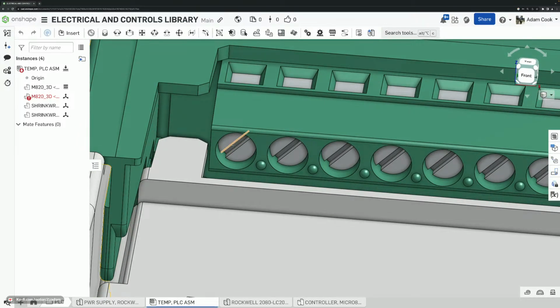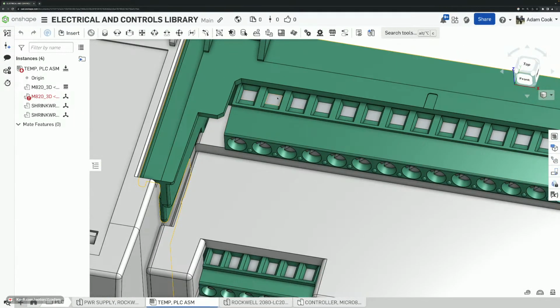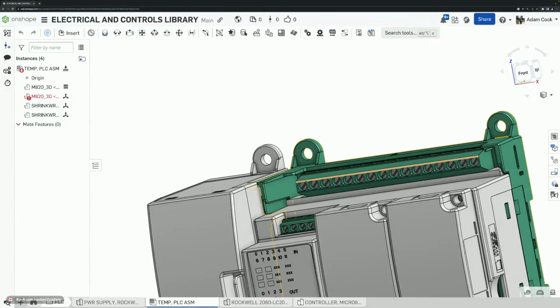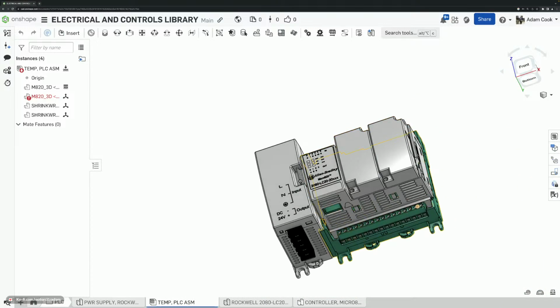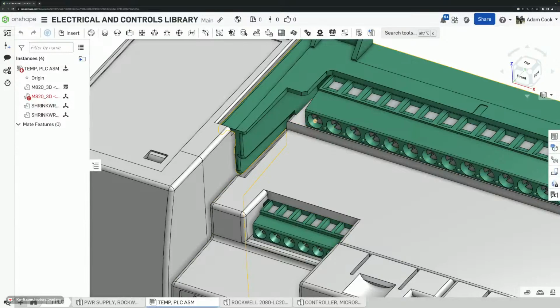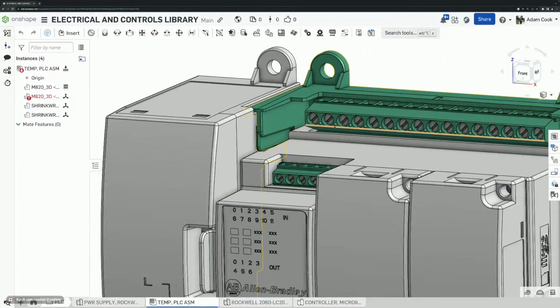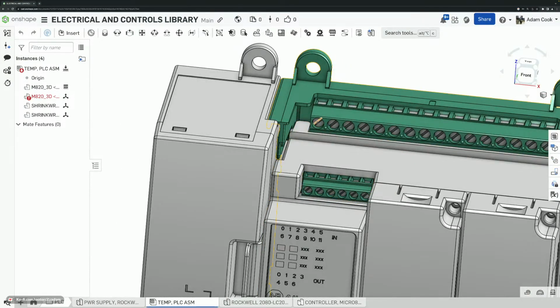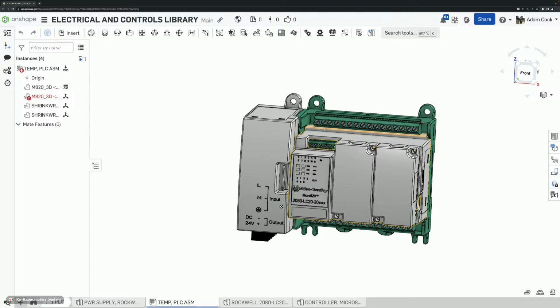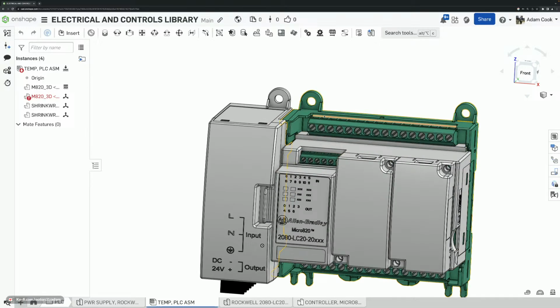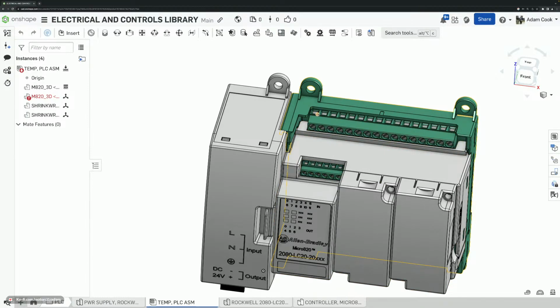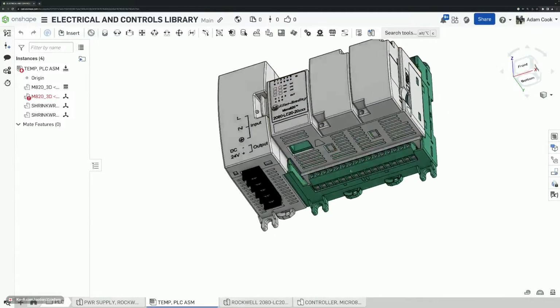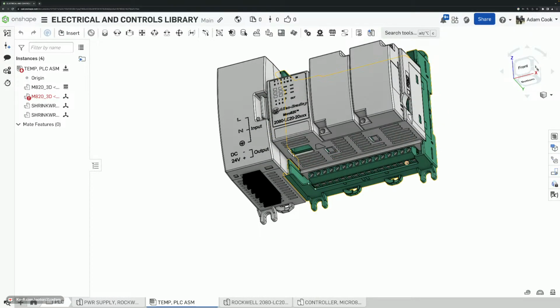And what you see up here are flathead screws for flathead screwdrivers. You can put wires in each of these openings and then tighten them up with the screws. You have a row of inputs up here and a row of outputs down there. So this is where the wires go. Don't worry about the details too much right now, because we will go through this in significant detail, but that's where you put the wires from all your sensors up here, and then your signal wires for your actuators are down here.